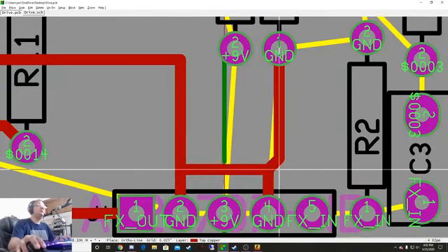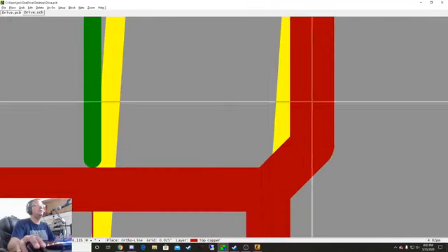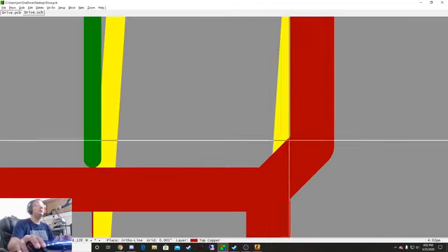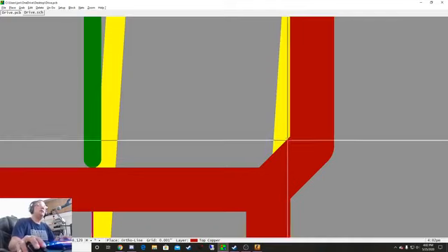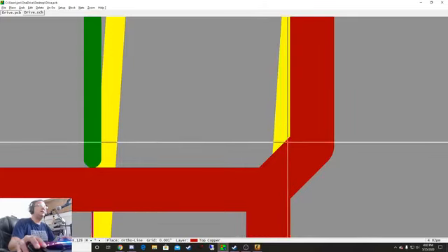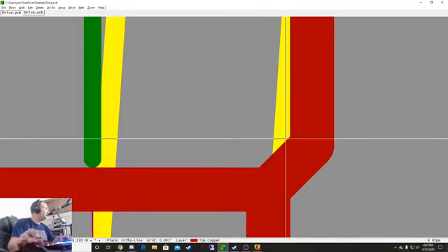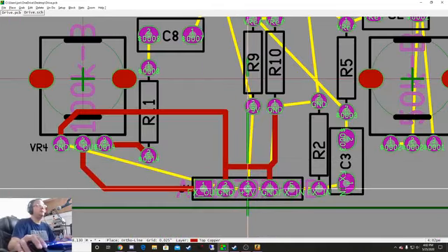Now, 45 degrees are recommended in all board layouts. The original reason was in the corner here. I got to put my, there we go. Right here in this corner, when they used to etch the circuit boards, it had trouble with right angles. So this right angle here, they would have trouble etching that out. So they would recommend 45s, otherwise this wouldn't etch correctly. That's not as much of a problem with modern circuit board manufacturing, but from an aesthetic standpoint, it's still recommended by most people.